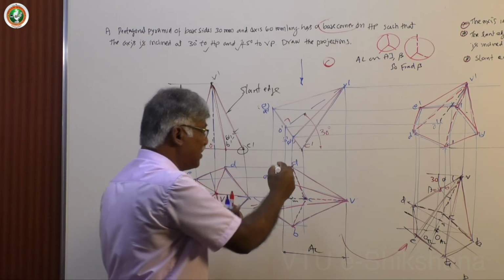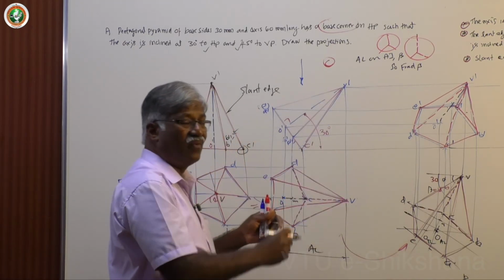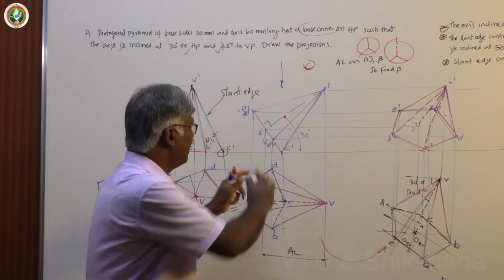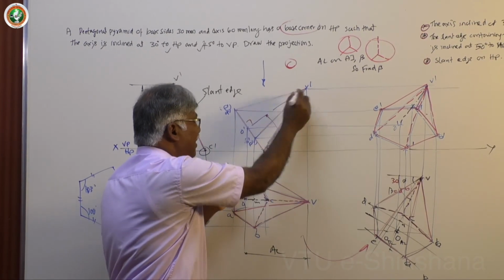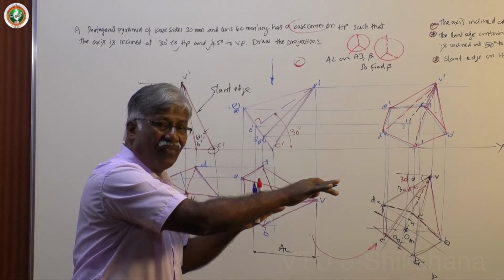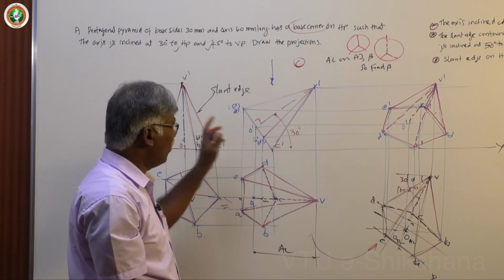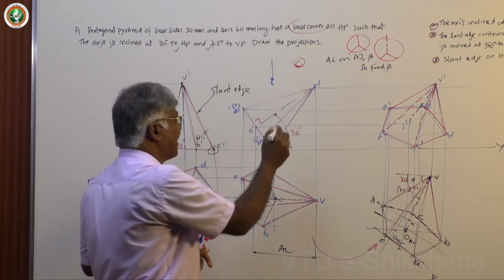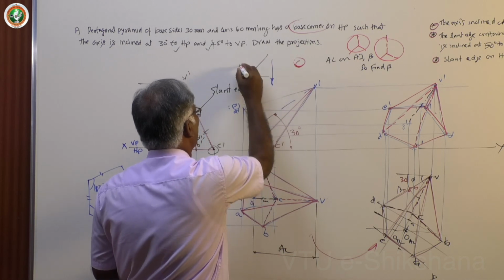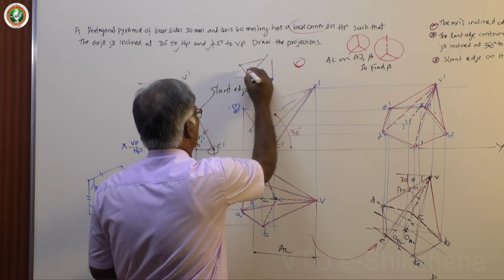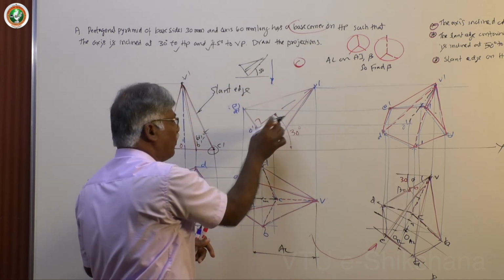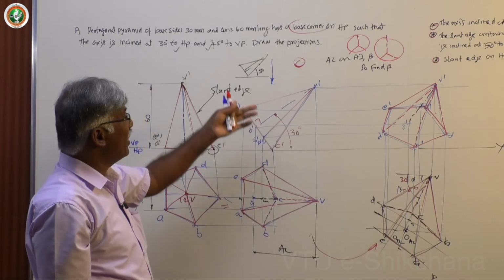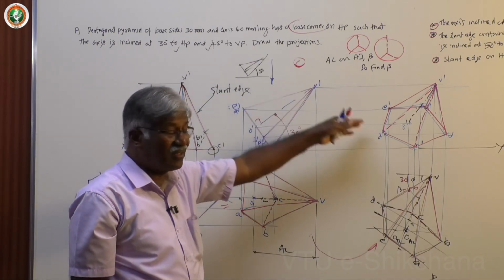For that what you do is, draw a line initially 50 degree or whatever given, I have given 50 degree, then rotate and see that this line is on that particular 50 degree line, that is all. Then do not worry about the axis. Here axis I had mentioned, in that slant edge method, you mark this is 50 degree. So again this type of problems you can solve, rest of the procedure is same. Then they may say axis inclined at some degree to HP.